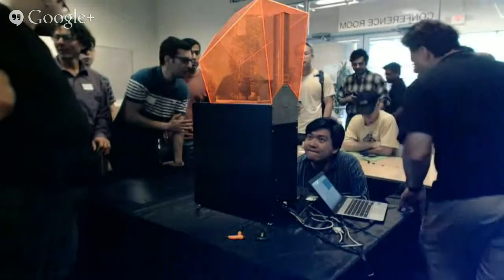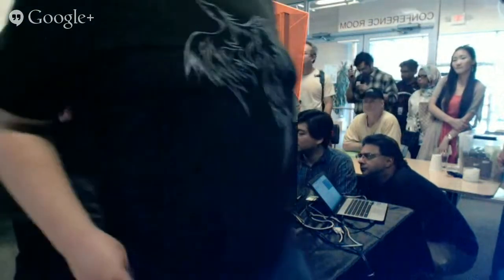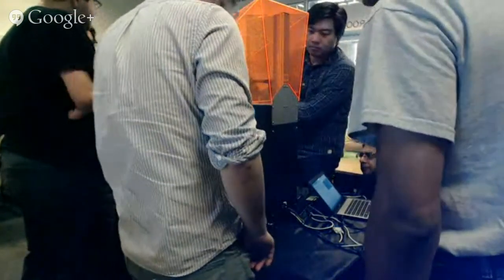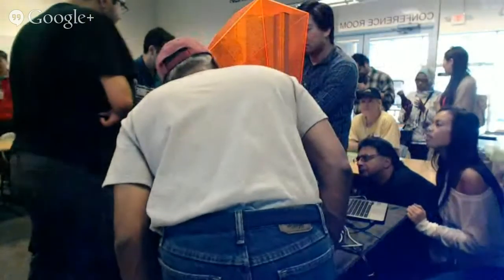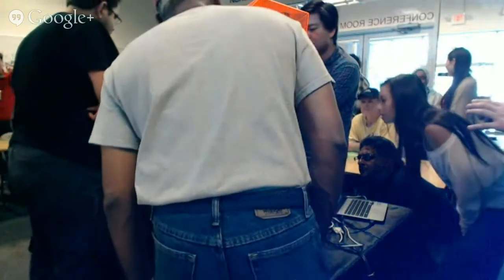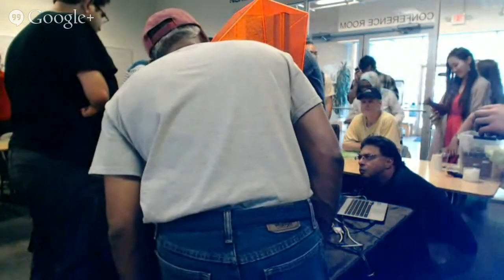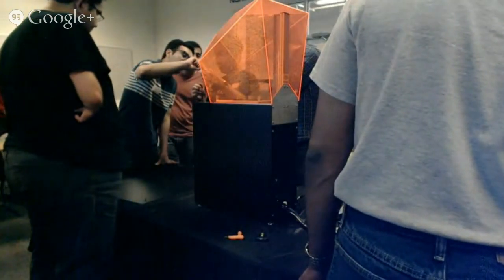It's not super horrible because liquid resin does not mix with water. So it doesn't float to the top the way that oils do. But generally it's not good stuff because liquid resin is quite reactive. So liquid resin will eat ABS, for instance. If I have ABS plastic and I poured liquid resin onto it, it would melt the ABS like acetone. And liquid resin, in general, you want to just keep it away from stuff, your own stuff also, because it would eat this plastic. It's pretty reactive. Yeah. I see.